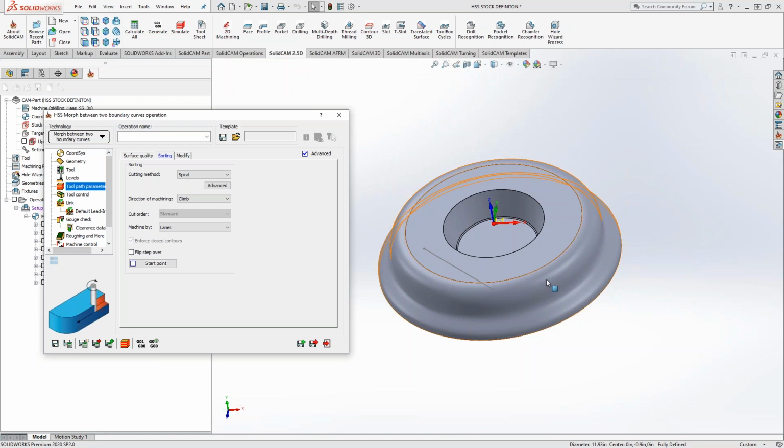That is definitely why I always come here, especially with radiuses like this. To go out and buy a radius cutter, like we were just talking about for that shape tool, to have one for every radius does get a little expensive, but if you're running high production, then you can definitely buy it. But by doing it this way, I get a nice smooth cut. And like Mark's saying, you get that beautiful finish.